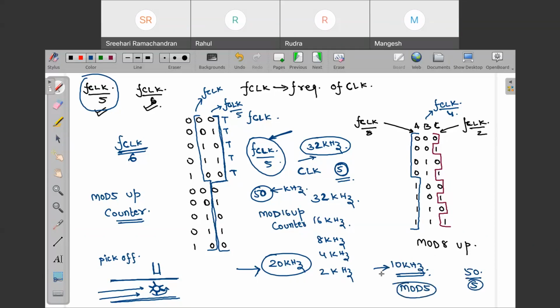Such a question I have seen, but for real life application, we usually don't use this circuit for dividing the clock. We have 555 timers, or we can create oscillators giving different clock frequencies. But using this particular circuit, even I am not able to recall where we use it. Are you getting the point?